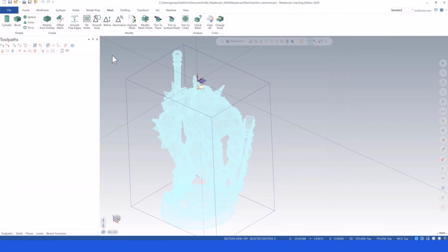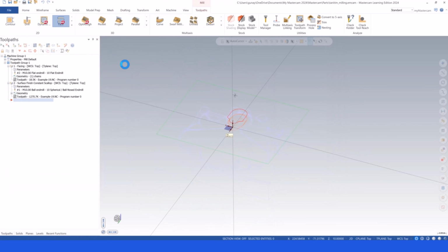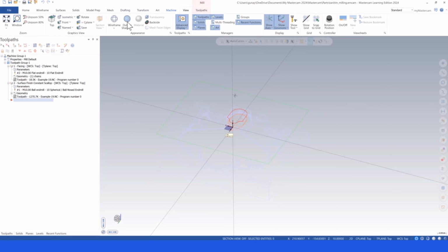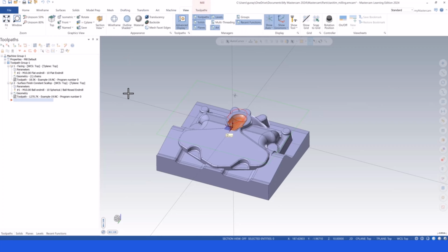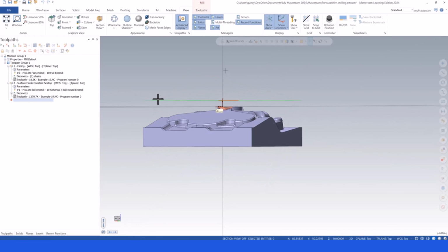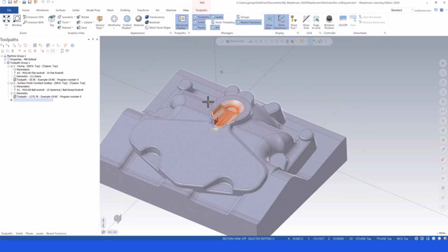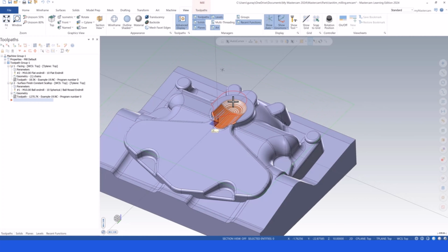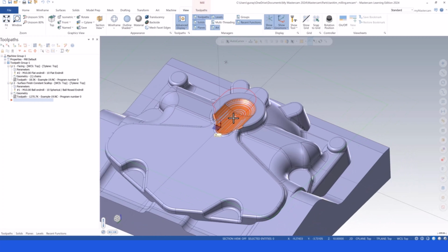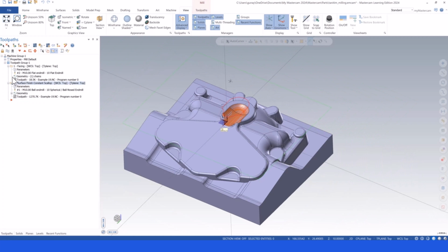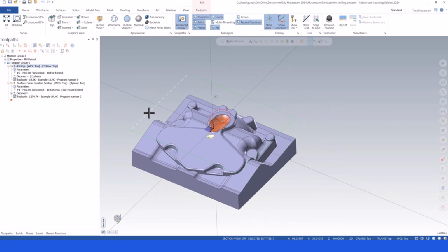And after that, of course, this is the MasterCAM meaning. You can create your model by using SolidWorks or CATIA or another CAD software. After that, you can turn to MasterCAM and extract your solid model to create your surface and your boundary, and after that you can easily create your 3-axis scallop toolpath, or you can easily create your wireframe like this one, and then you can create your face toolpath as well.